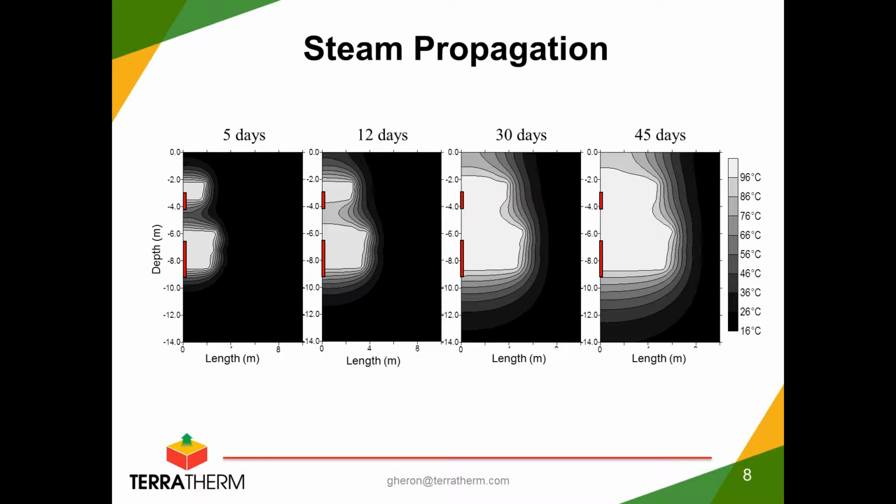And that's what makes this so different from conduction heating or ERH, that we actually have a convection component that is very strong and a displacement of the LNAPL towards the extraction well. It's exactly what they've been doing in the oil field for decades, but for remediation, it is extra important that you know exactly how this happens and at what rate the LNAPL is being displaced, so you can be ready to capture it when it arrives.